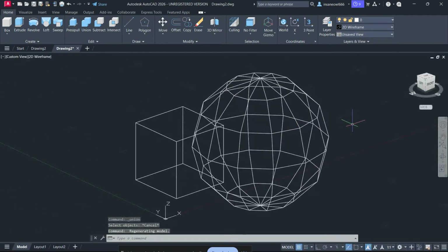In summary, AutoCAD error 97012 usually comes down to problematic geometry, edge alignment issues, or overly complex solids. The best fixes are to micro-move one object, clean the body, check solid validity, simplify the geometry, scale the model up temporarily, and join parts in smaller steps. If you follow those methods in order, you'll usually get past the error without having to start your entire model over.